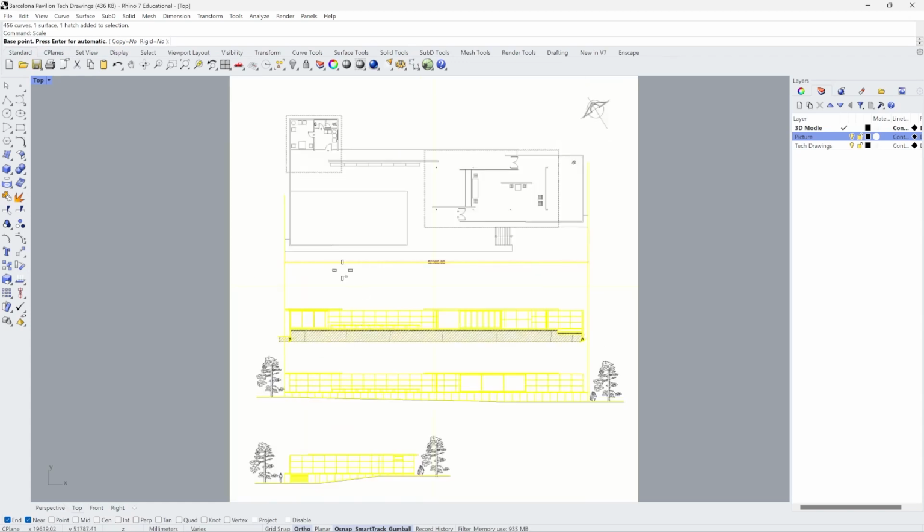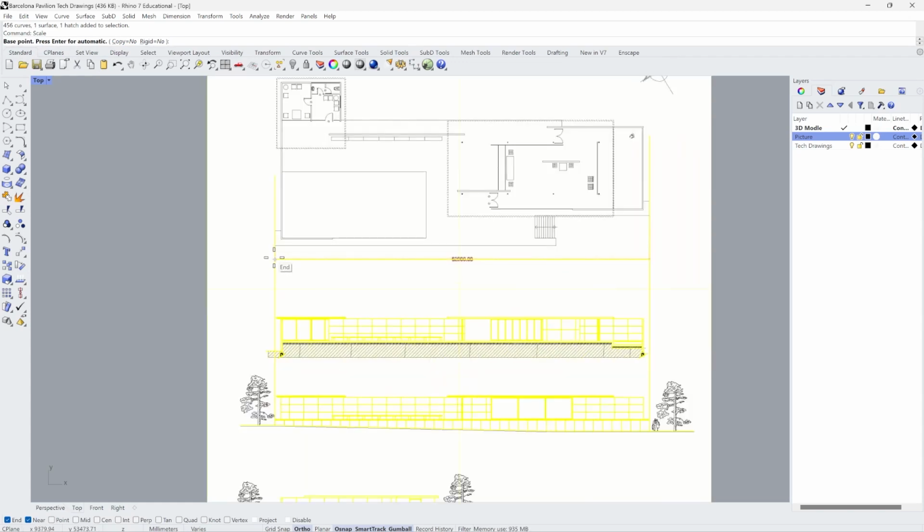The base point is a point that we select in space that's not going to move anywhere after you scale your object. So the whole object is going to be scaling from this point outwards or inwards. So this is a base point, and now it's asking us to either specify a scale factor or a first reference point. So my reference point is going to be the opposite edge of the lines that we have just drawn.